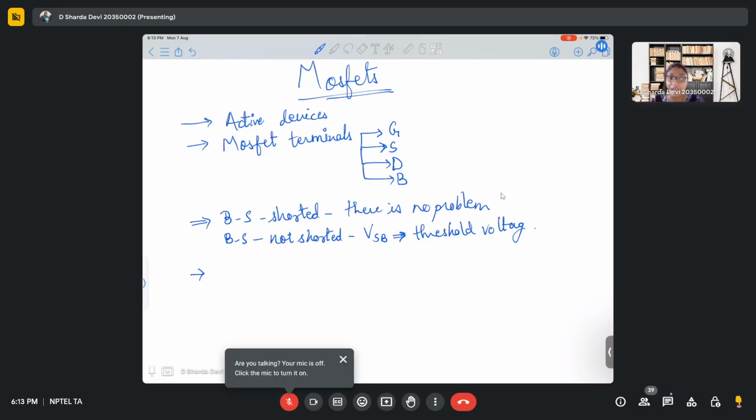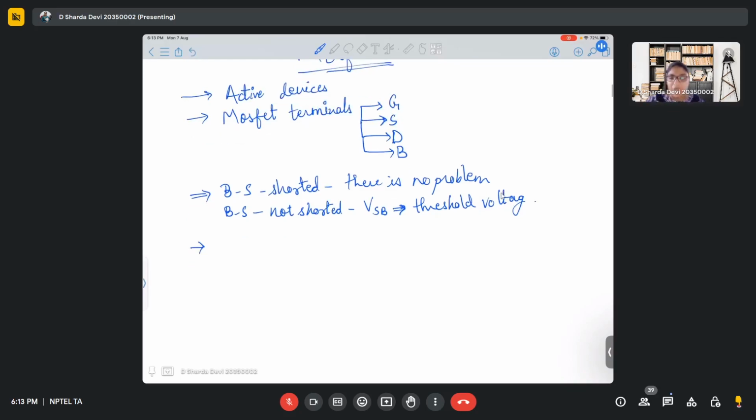That is where high voltage transistors are used for different purposes, and low voltage transistors are used for other purposes. We do have different circuits and different paths, and all these use different transistors. So it is very important to keep a note that body and source are not always shorted. But in our case, the majority of the time we consider them as shorted. That is the reason we don't even find body terminals in the basic MOSFET symbols that we use.